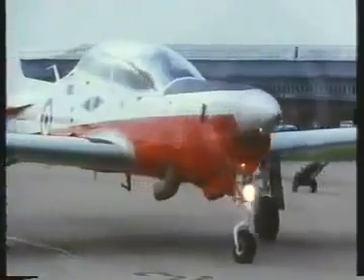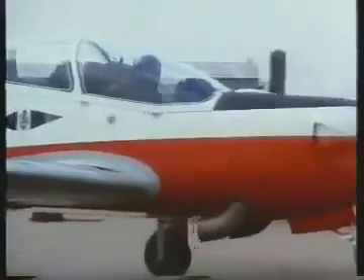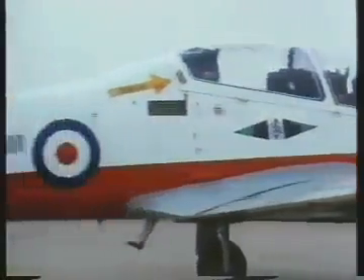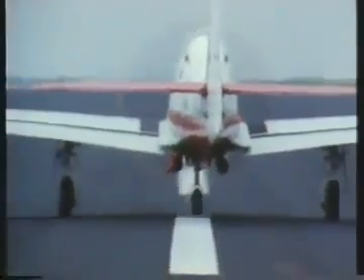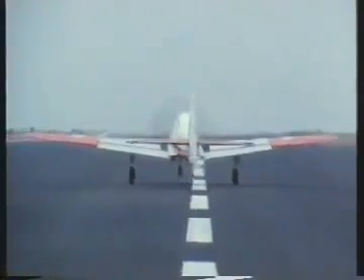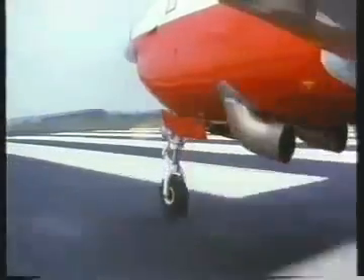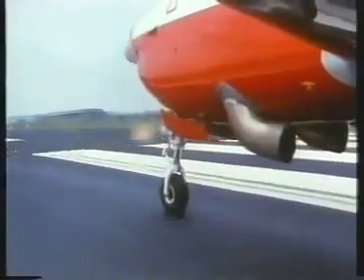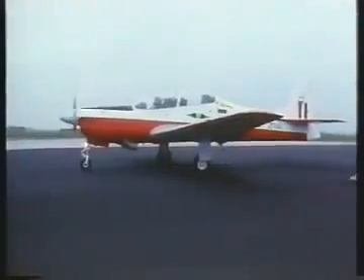Propellers also affect the handling characteristics of aircraft on the ground, particularly during the takeoff run, when they produce effects that try to swing the aircraft to one side. Ignoring crosswinds, there are four causes for this, but only two of them affect aircraft with nose-wheel landing gear.